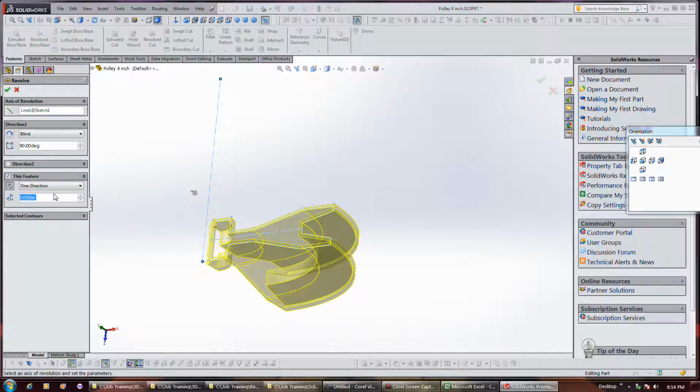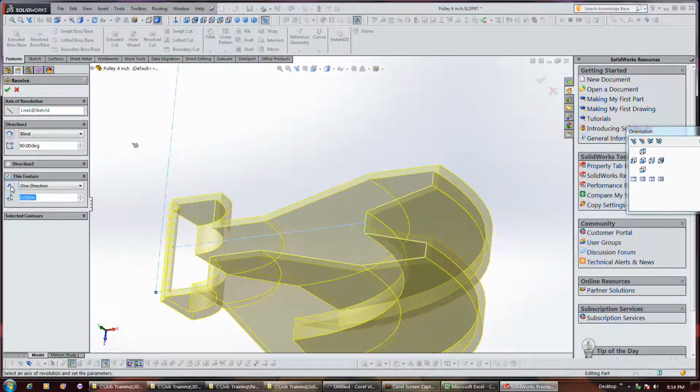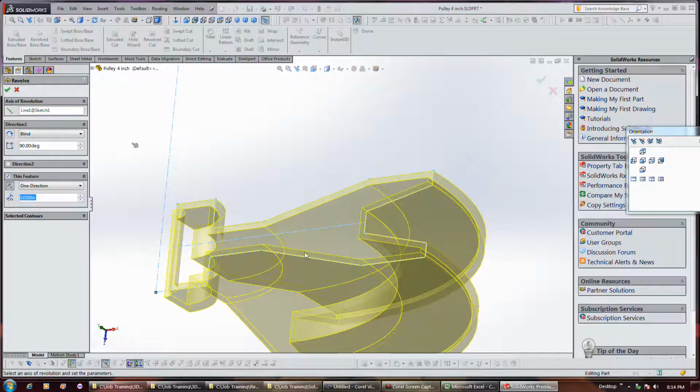With one direction, you can see that where we currently have it, this is on the inside, by 50 mil now. I changed it. That's on the outside. Our sketch is actually in the center, although it's a little hard to see. But this is actually growing it to the outside now of our sketch, and now it's on the inside of our sketch right there.